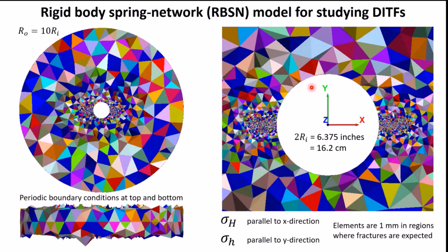But for fractures, you want to use DEM for fractures, really? So he doesn't need to do remeshing, right? Because the cracks can only go along the edges. Yeah, but another question is, what's your crack propagation criteria? So, bond strength. It's a local criteria for the bond strength. It's just bond breakage.